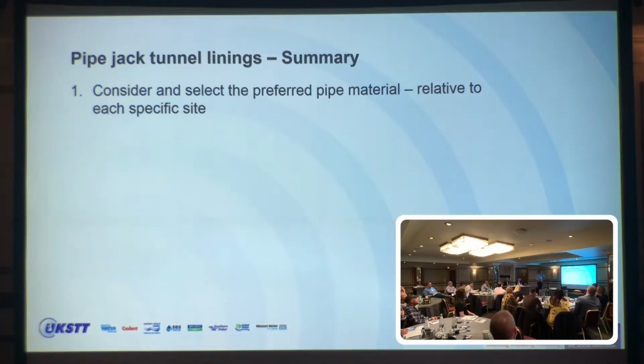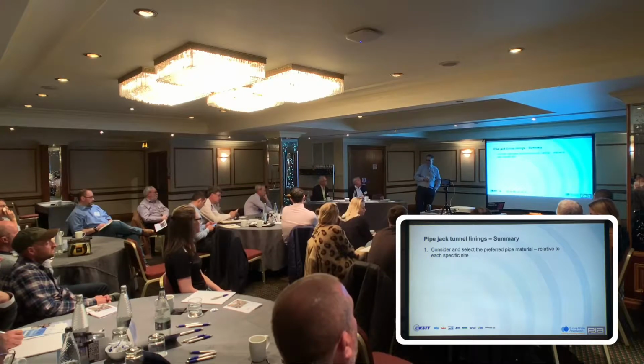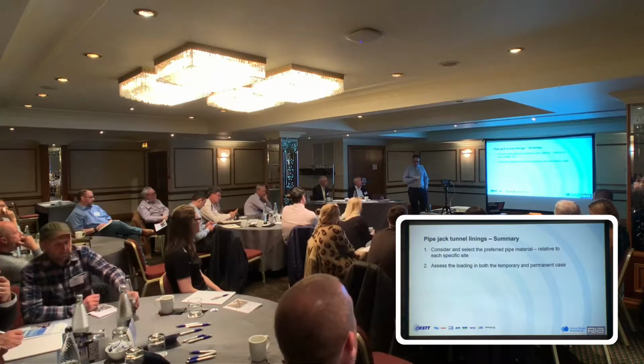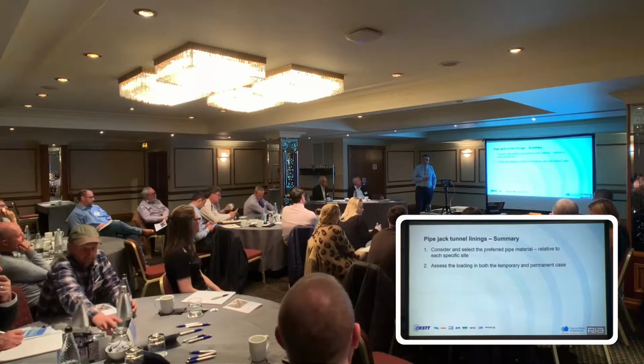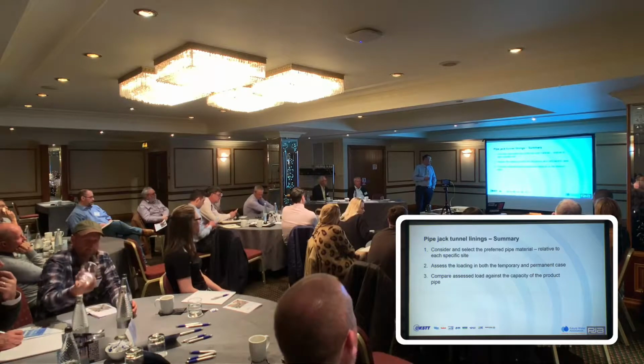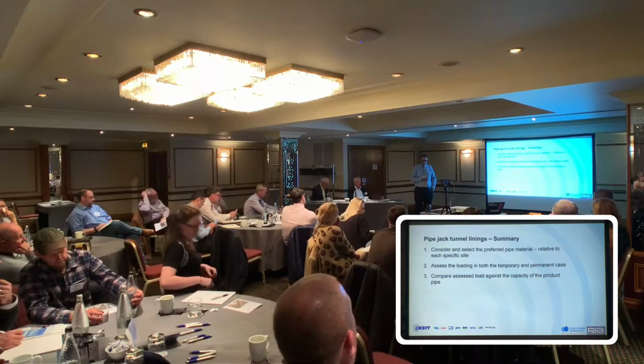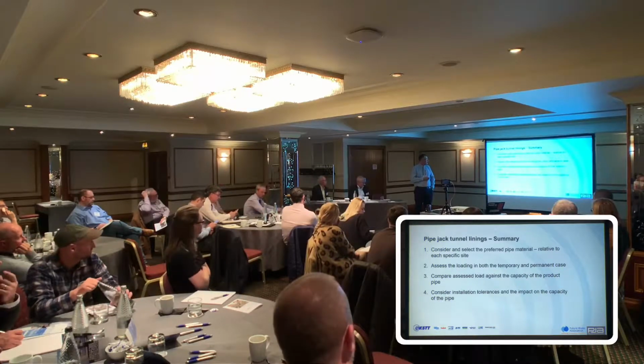So it's important to consider and select the preferred material. They've all got their own benefits, and I won't touch on those. We'll hear about that shortly, but they've all got their own benefits and their own limitations. So you should be thinking about why you want that. Dare I say, cost is a big driver, but it shouldn't necessarily be the dictating factor. You need to assess the load in both the temporary and permanent cases, and then compare those assessed loads against the capacity of your product pipe, whichever material it may be.